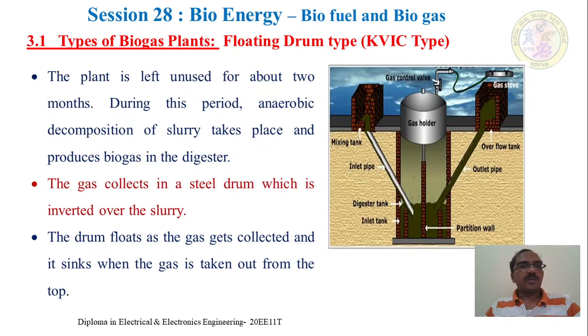Okay, so you will be in a position to understand how much gas has been collected, and depending upon that gas collection, you can control the biomass input over here. The gas collects in the steel drum, which is inverted, and the drum floats as the gas gets collected.